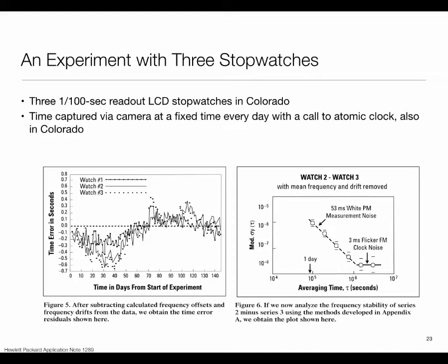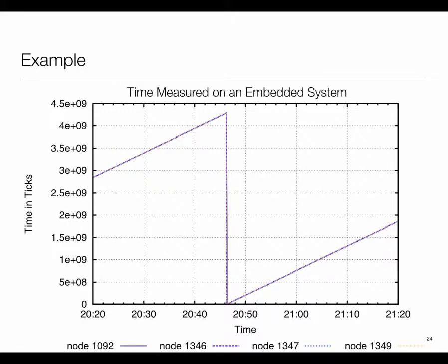So that's the experiment with the stopwatches, illustrating very nicely that clocks have instabilities. It can be compensated. If you look at our embedded type standard things, what you would see is that these systems, unlike our computers, do not come with a high-level notion of time. All they give you are timers. You measure time in terms of timers, and then you, as an application writer, have to establish your own time coordinate on top of it.